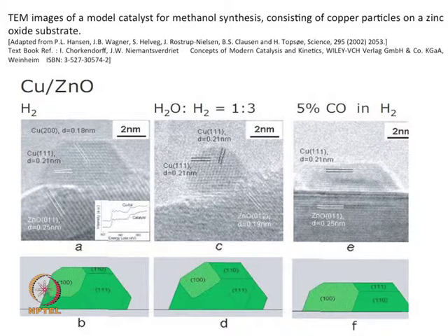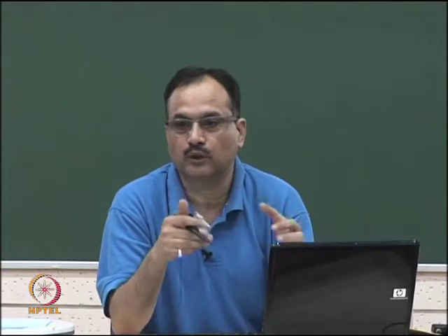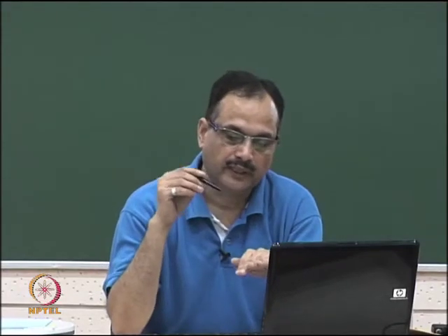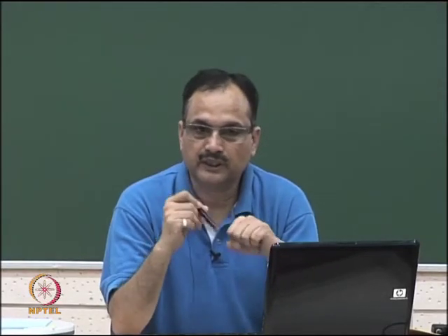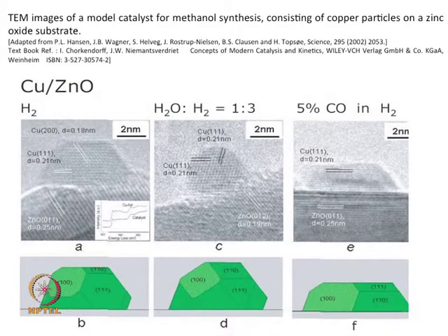So, you can calculate from different planes what the crystal or phase is and what the orientation of that crystal is, because when the reaction takes place, the orientation of that metal on a support is also important. This is what I am talking about here: the orientation of these planes. So, there are different structures here: 110 plane, then 100 plane, 110, and this is 111, right.